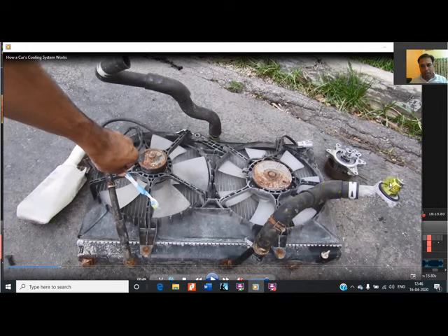And at the bottom side, one thermostat is also there. This is being shown over here, the thermostat, because you can't allow the coolant to go inside the cylinder block and cool the engine when the engine is running at the initial phase, because the engine is not heated up that much. Two fans are there for sucking the air, because induced air is used. One overhead reservoir is there, because the cap of this radiator is a pressurized spring-loaded safety valve, and after a certain pressure it releases the excessive coolant, which expands into this reservoir.